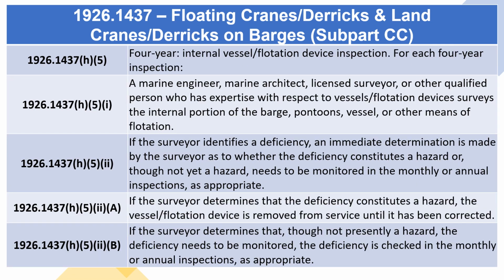1926.1437 H5, 4-year, internal vessel/flotation device inspection. For each 4-year inspection, 1926.1437 H5(i), a marine engineer, marine architect, licensed surveyor, or other qualified person who has expertise with respect to vessels/flotation devices surveys the internal portion of the barge, pontoons, vessel, or other means of flotation.